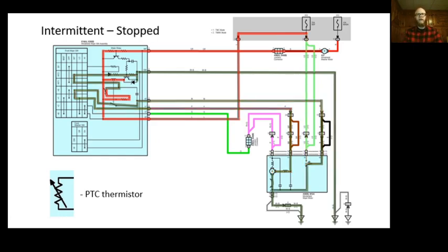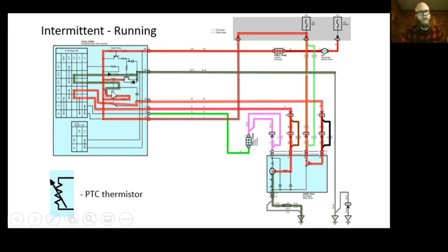So let's take a look at that again. It stopped. PTC thermistor needs to cool down. Alright, it cooled down enough, the relay clicks, it nudges the wipers, the PTC thermistor gets too warm. You can see the voltage just dropped back down again. And now my park circuit, which has been parked for everything so far, takes over, and that's what actually completes the wipe on this circuit.